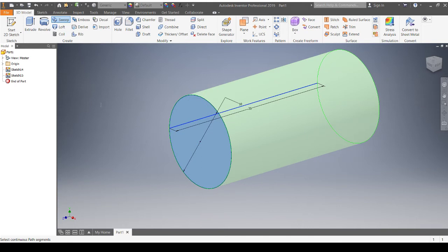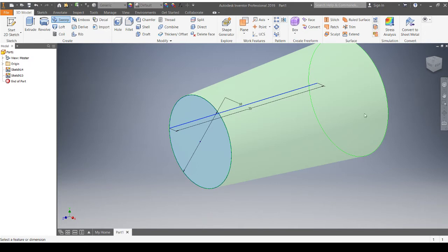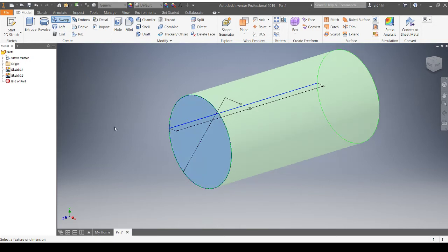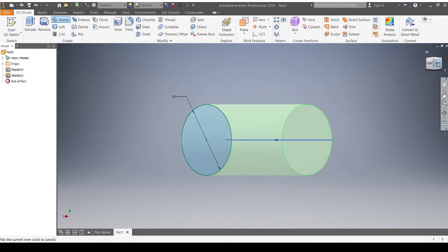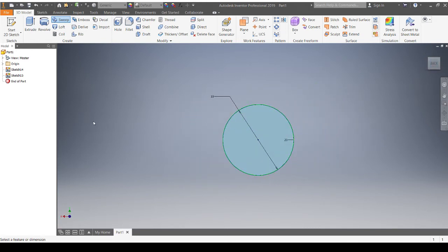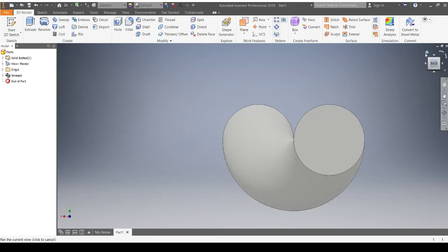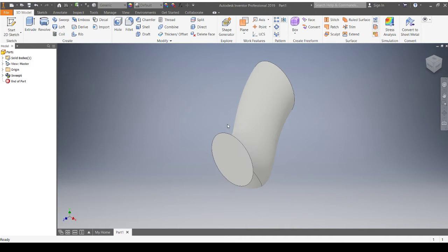Now we can use a couple of different features with this. You notice that there is the taper and twist features. The taper feature makes the final shape bigger than the original shape. Now for the twist, you can change this to degrees to make it a little bit easier. I'll flip this around so you can see it. The twist feature twists the end shape about the path that we already created. So if we hit 180 degrees, you can see that it'll twist around this path at 180 degrees.